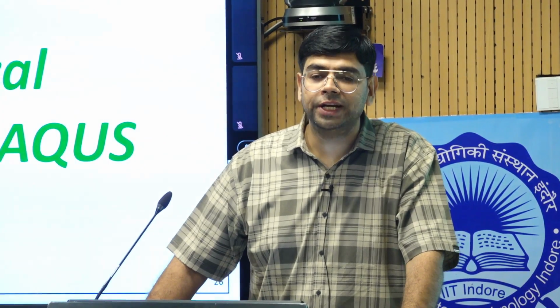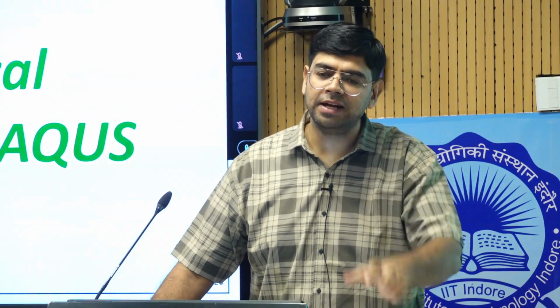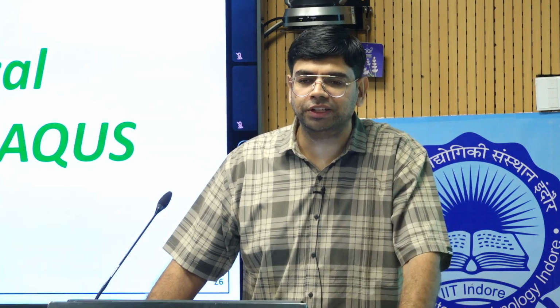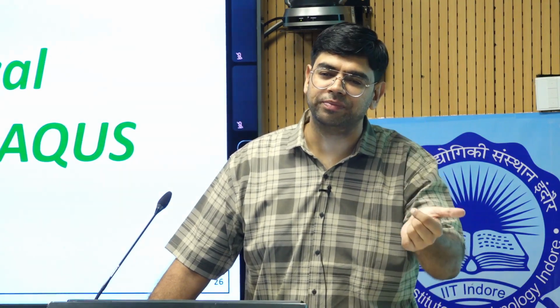FEM is also a tedious process. If you have a complex geometry, you need to mesh it; you have to select the element to mesh the entire geometry of the equipment that you are devising. So it can also become computationally very expensive sometimes to solve the equations using FEM.